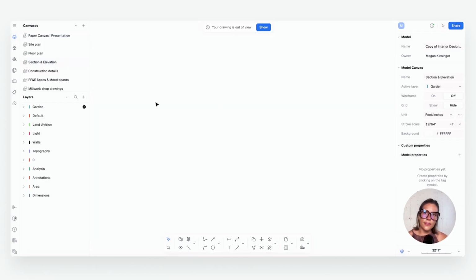Before we do anything, we're gonna start by setting up a layer called sections. You'll just go to the plus button, hit layer, and call that sections. And then inside of it, we are going to add a nested guidelines layer. What this will do is allow us to create guidelines for different heights of things, for instance, the floor, the ceiling, the windowsill. And by putting these on their own layer, it will make it easy for us to lock or hide it later.